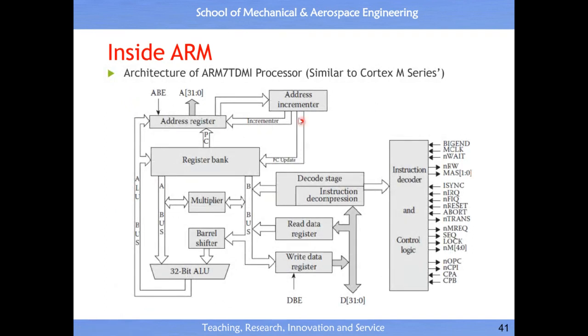So this is some background knowledge for you to know. And Cortex-M4 basically follows this blueprint of a design. From here, this is the hardware control, then the ALU is here, and you see 32-bit. Then you will see we have an address bus and an address register, and another address bus here. The data bus is here: you see 32-bit, from bit 0 all the way to bit 31.